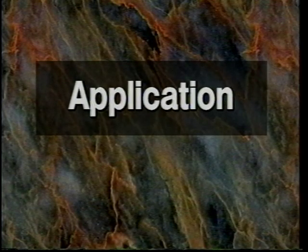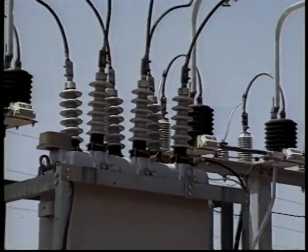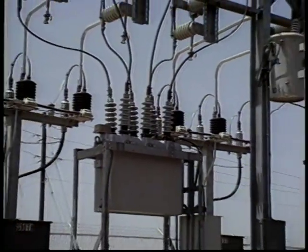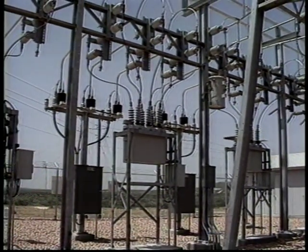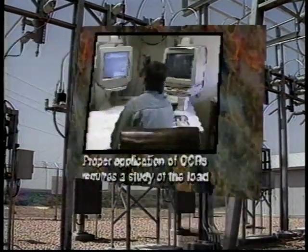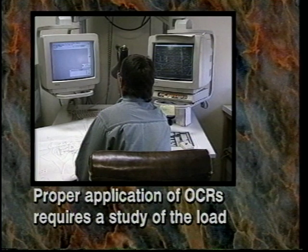Application: automatic circuit reclosers are used in distribution substations and on branch feeders to protect distribution circuits and to switch them. Proper application of OCRs requires a study of the load and the short circuit characteristics of both the protecting and the protected equipment.